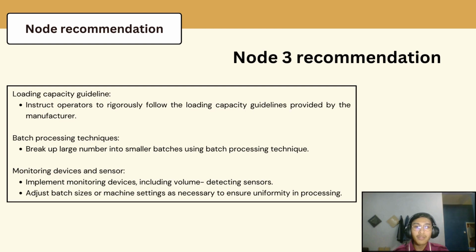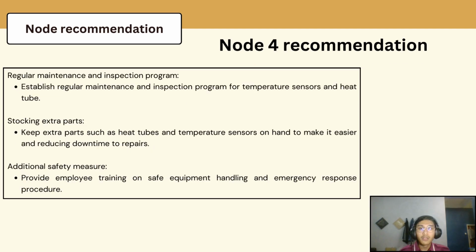Implement monitoring devices including volume detecting sensors and adjust batch size or machine settings as necessary to ensure uniformity in processing.